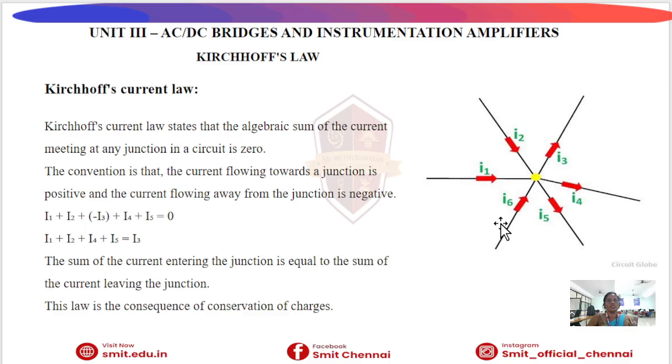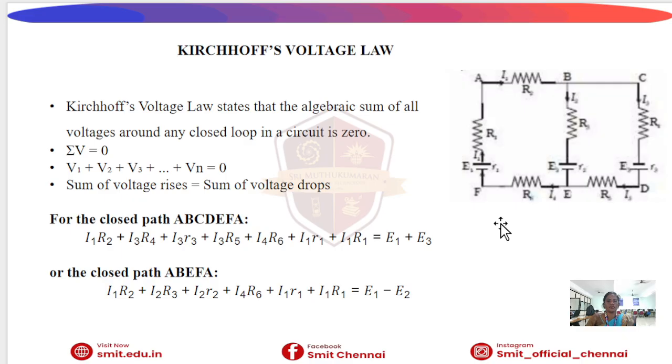This law is based on the principle of conservation of charge, which states that electric charge cannot be created or destroyed. Therefore, the charge cannot accumulate at a junction and hence the current entering must equal the current leaving. Kirchhoff's current law is very useful for solving complex circuits using nodal analysis.